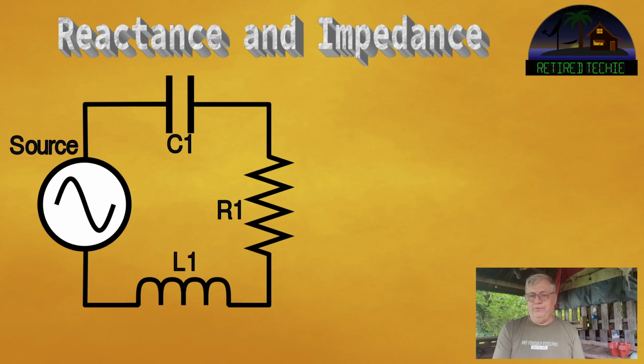So for example, in our circuit here, we have a coil L1, whose inductance is measured in henries, but what we're after is the inductive reactance, which is X sub L equals 2 pi times frequency times the inductance in henries, and that's measured in ohms. We use 60 hertz, so our frequency would be 60, and like I say, this will vary depending on your frequency.